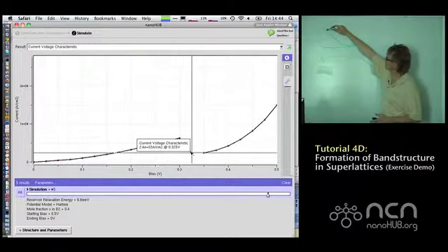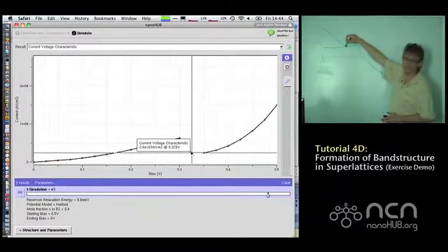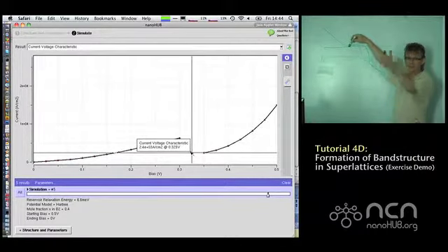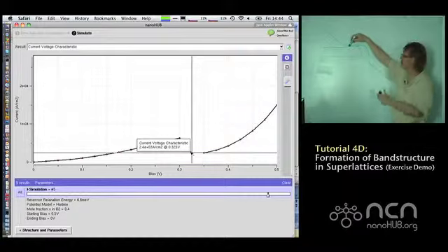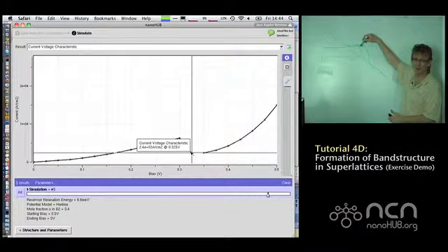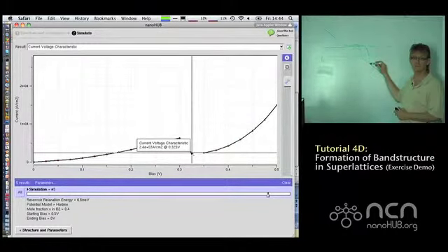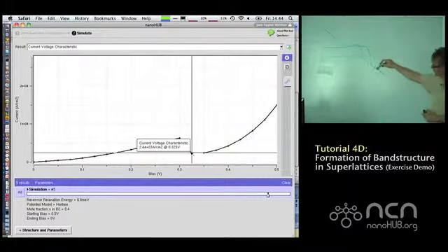And as it starts to hit the Fermi sea, this bucket of charge or this bobber gets filled up with charge and it gets repelled out, right? So it'll start floating on top of the Fermi sea until the potential that is actually yanking on it is strong enough to pull it all the way down. Okay? And then it'll follow basically this linear law because there's nothing that pushes it up.